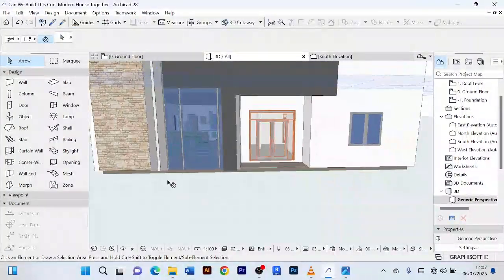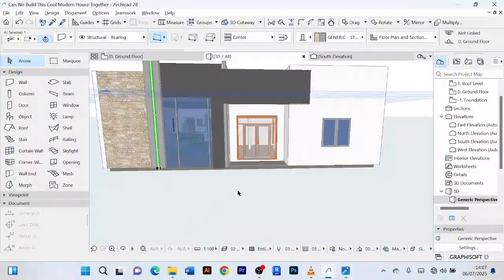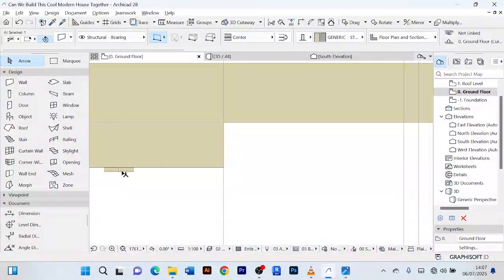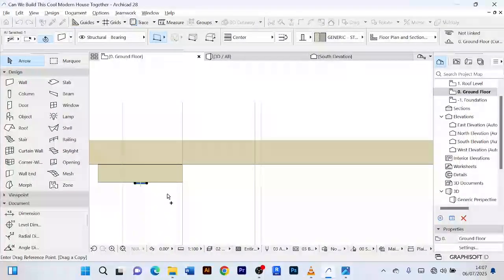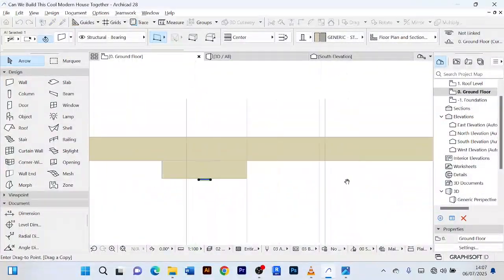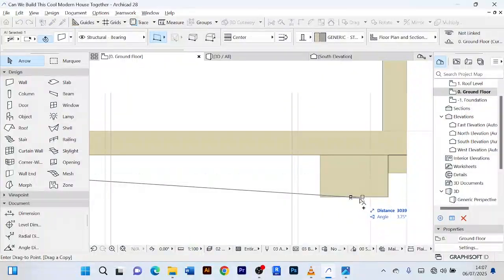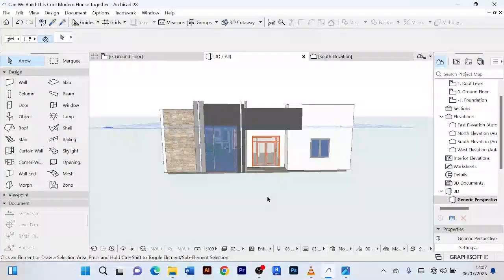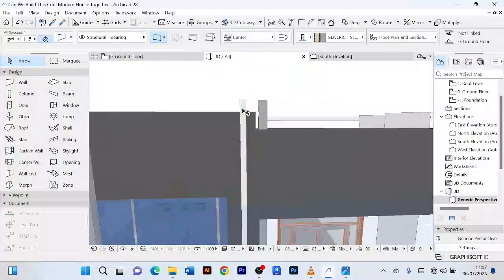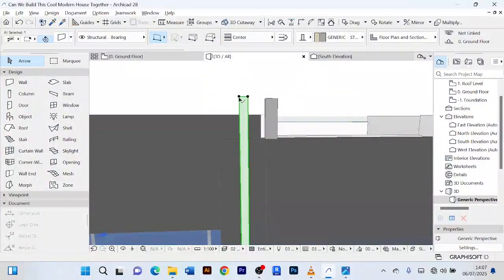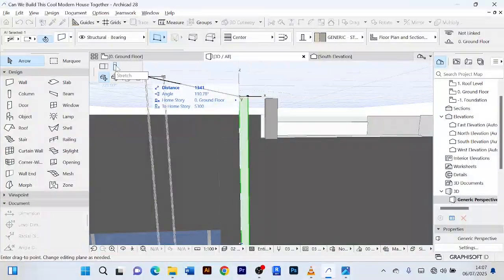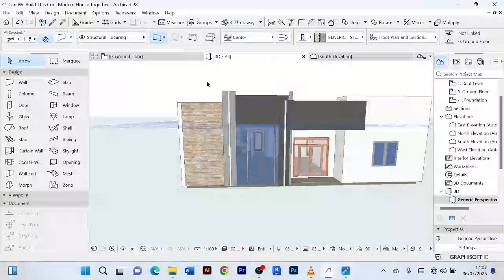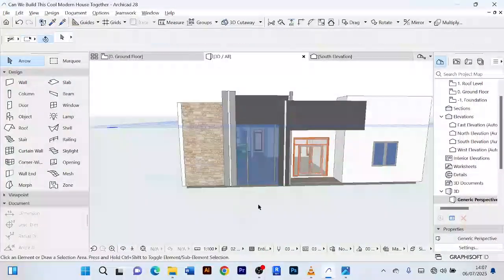So we're going to create another thing here. You see this wall here. So also create it here. So you come to the ground floor. I can just simply pick this. I'll Control Shift D to drag a copy of it. I'll bring it here on this one, just like that. I come to the 3D. You see we already have that. So I can just reduce the height. Can actually reduce the height from here. You just click on this, you come to this one here that stretches it downwards like that, just like that. You have that design. Deselect all,